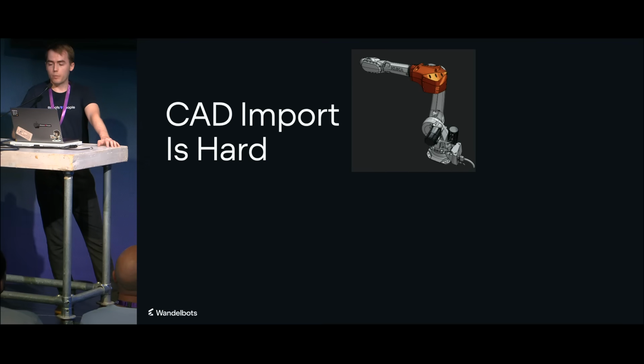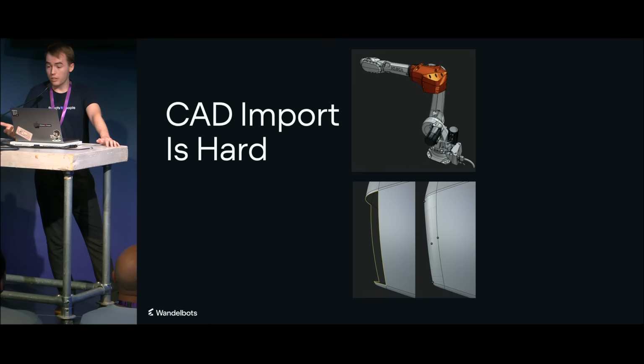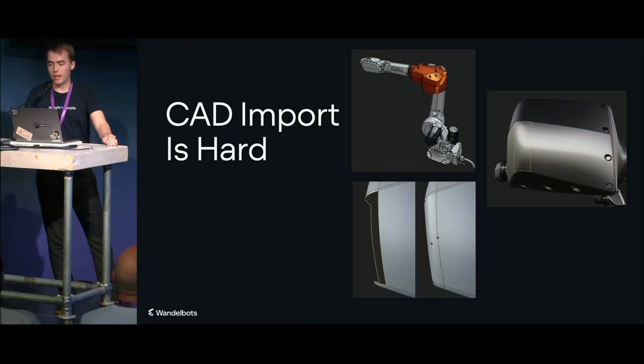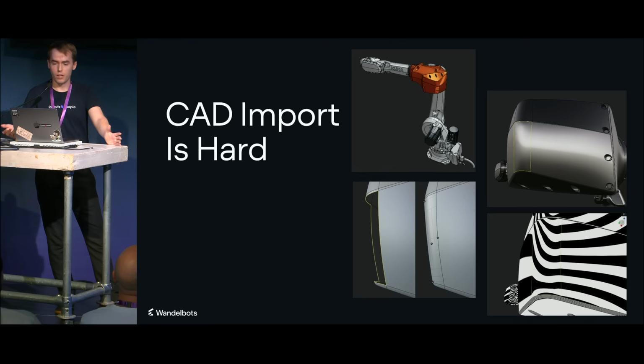Here's an example of the manual CAD workflow that follows. The geometric accuracy is one reason why we do this import, but visualization is equally important. So missing faces and stuff like that can't really be tolerated. And filling in some gaps is just a little bit more complex than pressing F in Blender to fill it. Curvature continuity has to be restored carefully, and when done properly in CAD, the result is a smooth reflection with clean surfaces that will work technically and also visually.